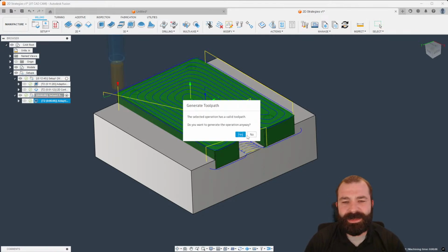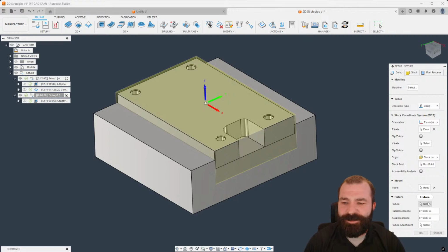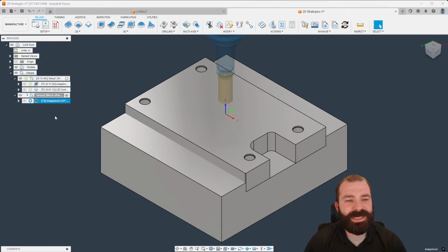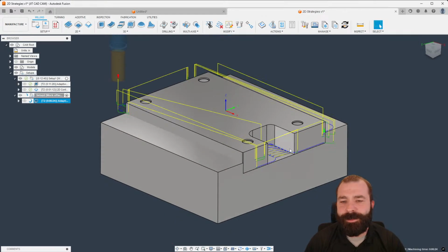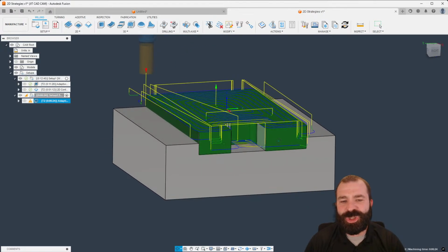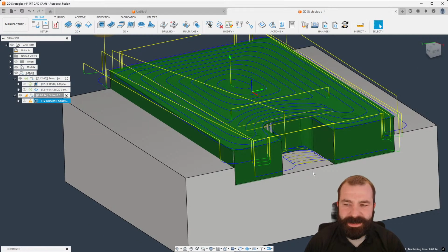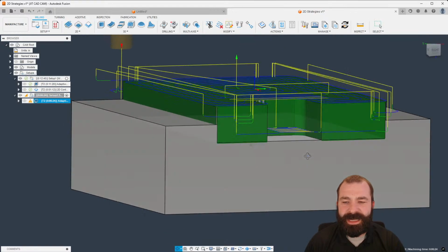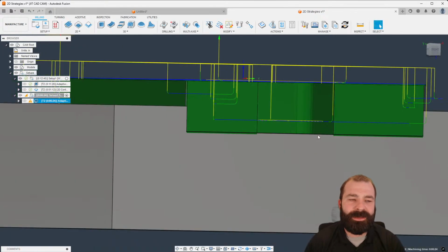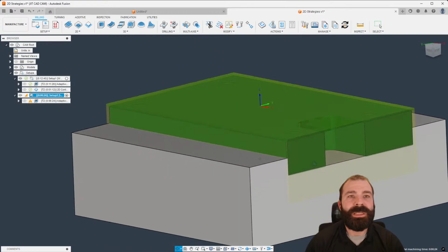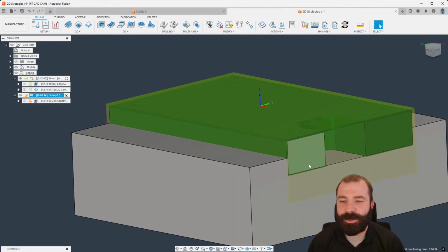It's when we start machining back the other way and you're using a fixture, right? As you can see, I'm now calling that my fixture to hold my part. The tool path itself may or may not actually machine or achieve where it needs to machine. As you can see, we're working back down that other way, but what is happening is we will not get closer than whatever our fixture offset is. So if my fixture offset is 200, we're always going to stay away from that fixture by 200. So something to keep in mind as you're doing this.